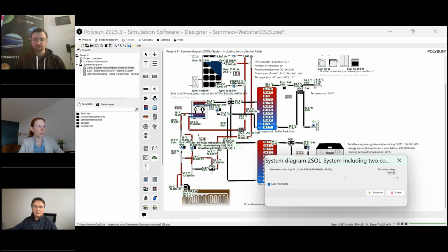So you can really determine all the temperatures that you actually have. And of course, they are quite variable, also depending on the irradiation and the weather data, but also on the tilt angle, on the orientation, and the flow rate that you apply for your system. And that helps you also to show how much the PV, so the electrical part, can benefit from this constant cooling that we do here.